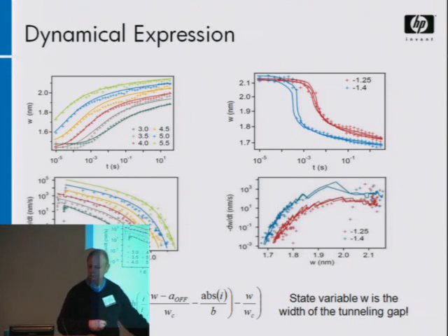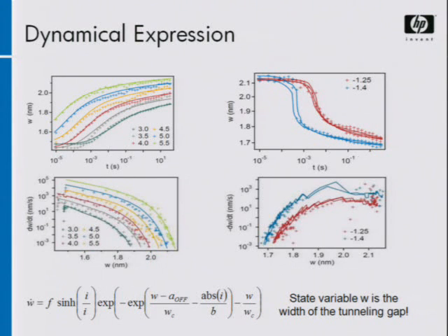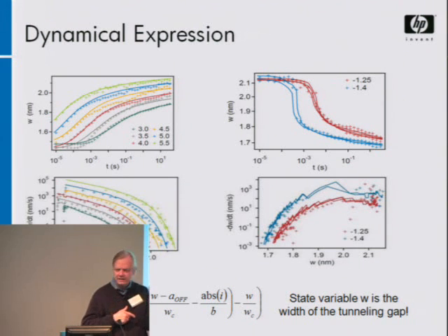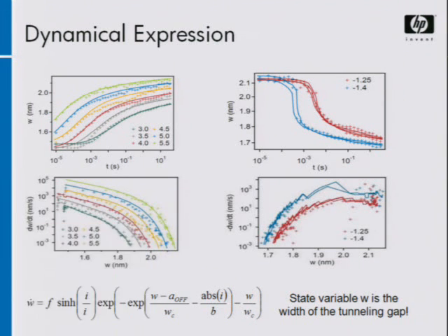All right? Now, the reason for that is because we've got nonlinear conduction, we've got tunneling, so the current voltage characteristic is exponential, and we also have exponential drift. The drift velocity is exponentially dependent upon the field. So that winds up giving you an exponential of an exponential. This is tremendously nonlinear, and that's actually very exciting because the more nonlinear a system that you've got, the better it is for computation. And the larger range of time you have accessible to you for this system.